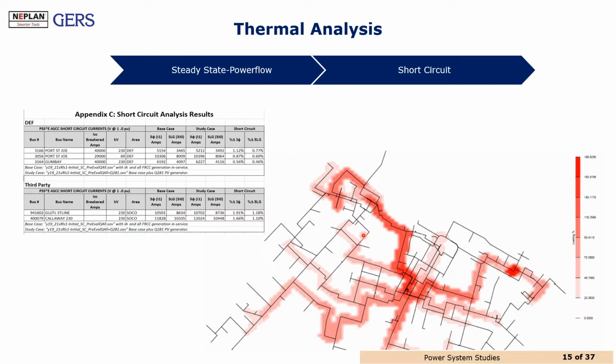In this case, it is also convenient to mention here that the short circuit analysis will contribute to check the ratio of the change on the short circuit levels. And we can see how we can compare a base case with a new study case. The grid code requirements define the maximum allowable change or delta that the new connection request should accept or not.